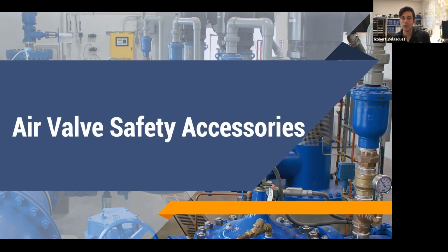And so if your vault floods and you have an air vacuum valve in there and you have a vacuum event, that air vacuum valve is going to open up to let air into the water system. If you've got water in there, it's going to let the water in. And if you've ever been in some of your dirtier vaults, you don't want water from there getting into your protected water supply. That is a cross-contamination risk. So you need to make sure that you don't have water coming in during a flood.